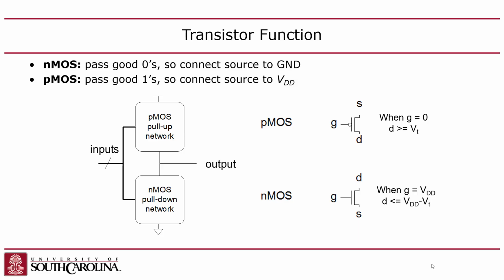It's actually a negative threshold, something less than negative 0.7 volts or something like that. How do you get negative? Well, that voltage on the gate is relative to the source, and the source is connected to VDD. In other words, because the PMOSs respond to a negative voltage, you have to get them up to VDD. And because the NMOSs respond to a positive voltage, you have to get them down to ground. Basically, that serves as their reference.